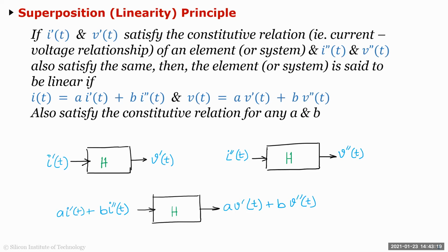Superposition is only valid for LTI systems, right? So you have a linear system, and if you give an excitation and get an output, and you give another excitation, you get another output. The principle says that if you sum the inputs, then the outputs also will sum. So you take arbitrary inputs, and if you can break them into linearly independent ones, which is called the basis form, then you can individually calculate them and then sum the outputs. That makes it much easier to solve a lot of complex systems.